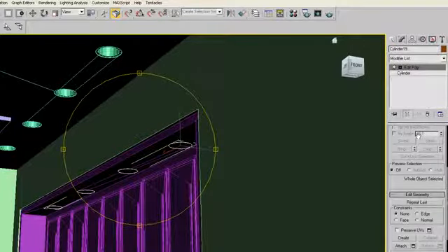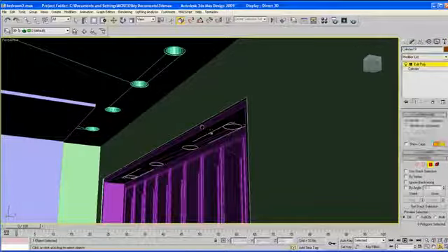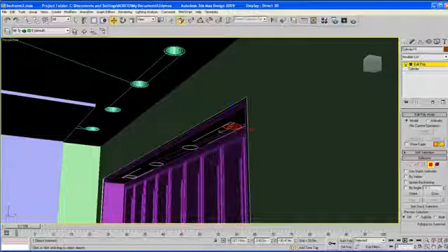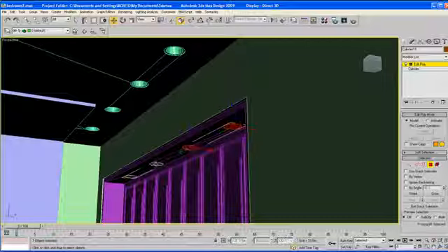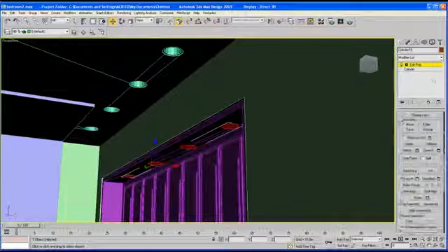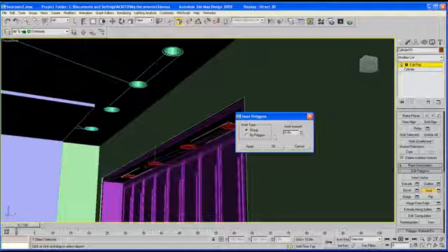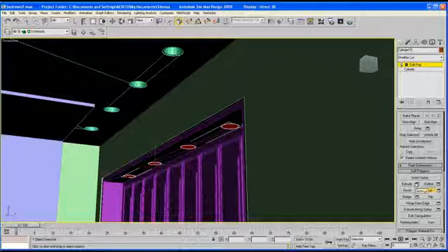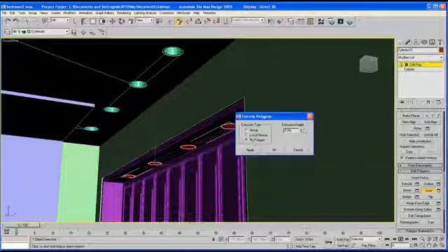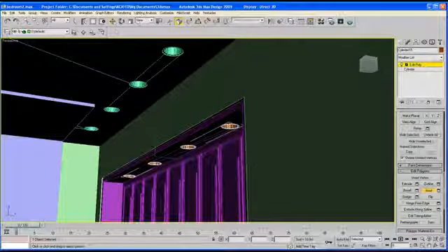Okay, go back to your modifier panel with the 4 cylinders selected, and then select polygon, and then get these parts in the inside. We're going to inset that one more time. Just hit the settings, and I think that's pretty good. Then extrude them by polygon inwards. Say OK, and there you go.